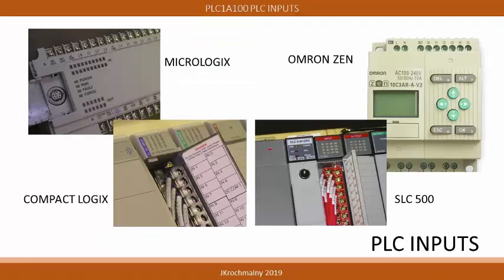It is important to understand that although PLCs come in various sizes and complexities, they all have the same operations. Utilizing this example, all PLCs will have input sections and are used to sample controlled conditions. Even if the PLC input section looks different, they will all have certain diagnostic LEDs. Technicians can refer to these diagnostic LEDs for input device status.